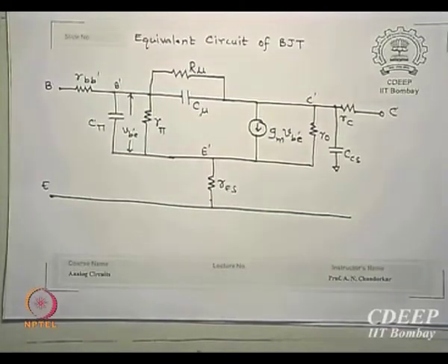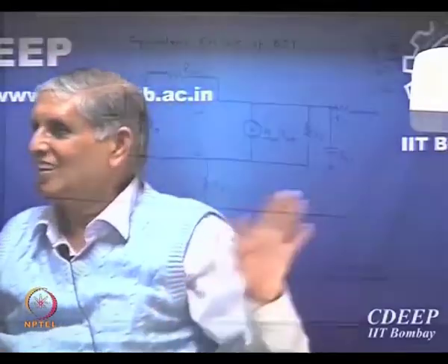Is that okay? Wherever a transistor appears in an actual circuit, between these terminals I will just replace it with this equivalent circuit, and then solve the Kirchhoff law with external components connected here, here, here, wherever they are. Is that correct? Some more loops, some more nodes, solving. Okay, is that okay?